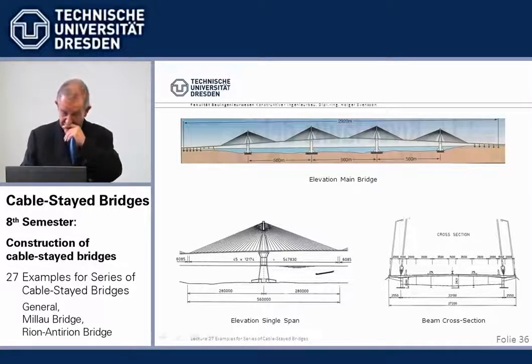Now, each unit consists of a solid, rigid pier with a total length of 560 meters beam supported by stays. We have here the cross-section. I would nearly say an American cross-section. That's the way we designed our bridges in the US. Open cross-sections, not boxes, and a composite bridge deck, because they also have a problem with welding, apparently they have in Greece. So that is the most economic solution.